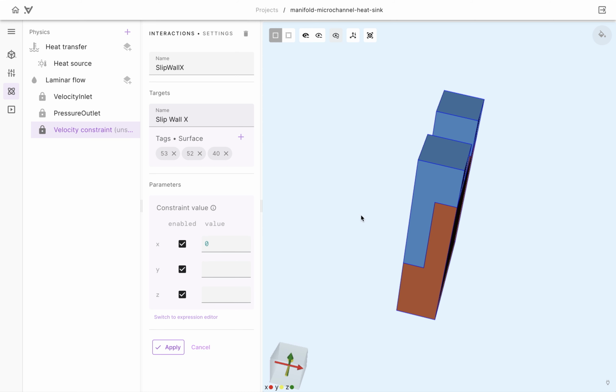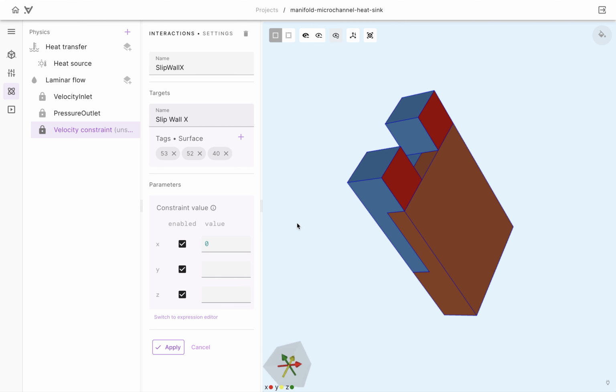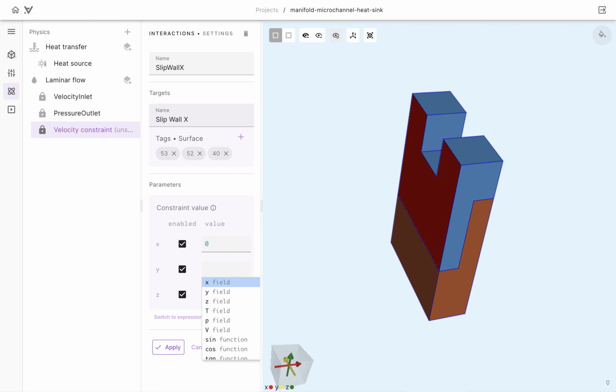So we stop the flow movement in x direction. And for other two directions, we can set the component wise velocities. This will simply set the velocity from the fluid region. So it's equivalent to setting the Neumann boundary condition. We can also deactivate the other two components, and this will be also equivalent to Neumann boundary condition.